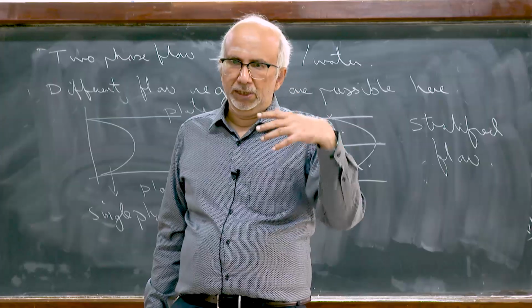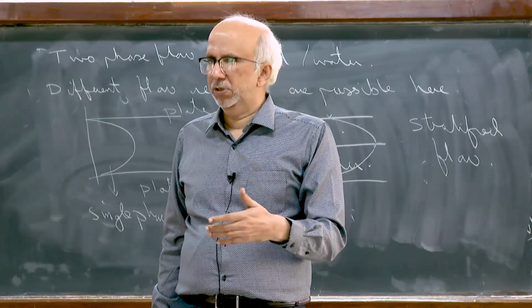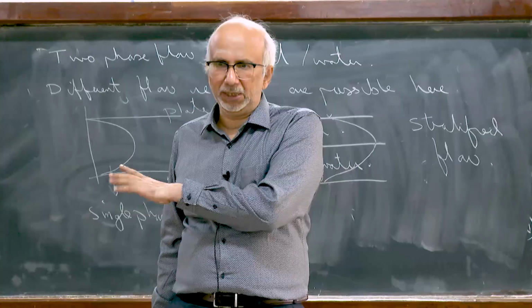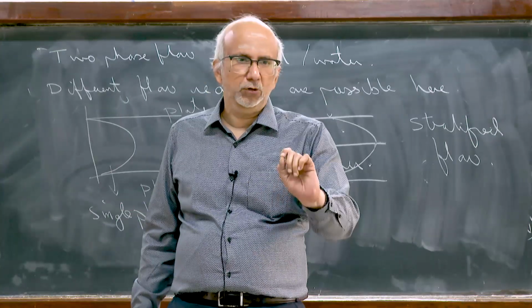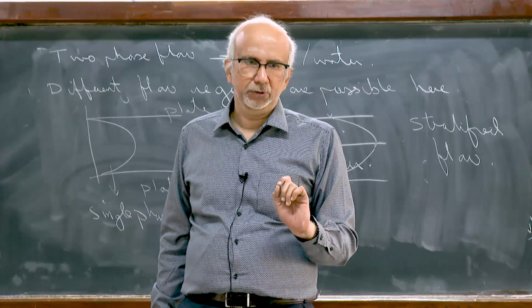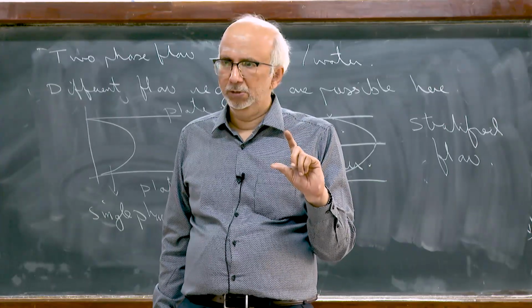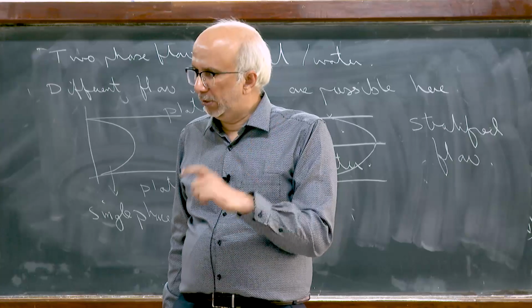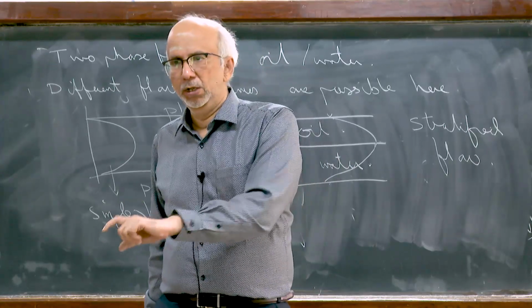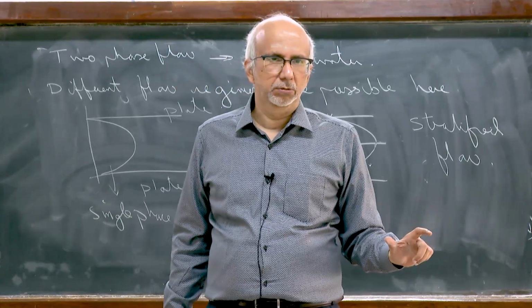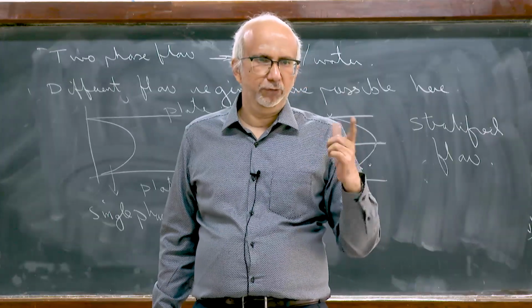If I say low, inertial force is less compared to viscous force. Similarly, when you talk about Weber number, capillary number, I bring in the concept of surface tension. So high and low is a totally useless thing to say because I need to tell you high with respect to what, low with respect to what. The ratio of forces is important.